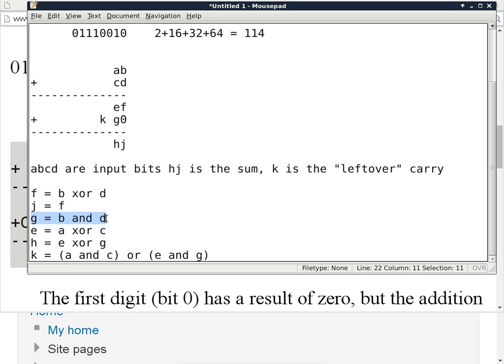And we can look at C and R as those are outputs of whatever operation we perform on the first digit. So this is the output, this is the output, these two are inputs. I'm using the notation of Logisim. So we just have, we built it, just an exclusive OR gate and an AND gate. If I were to ask you to write out the actual gate configuration inside a half adder, would you know how to do that?